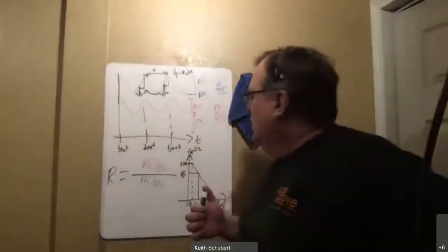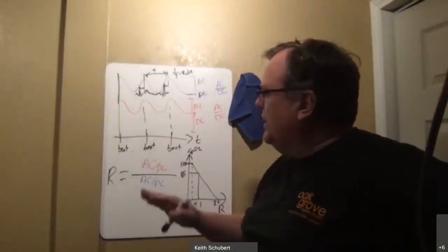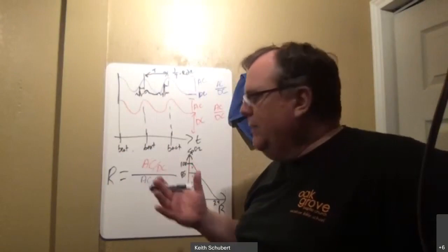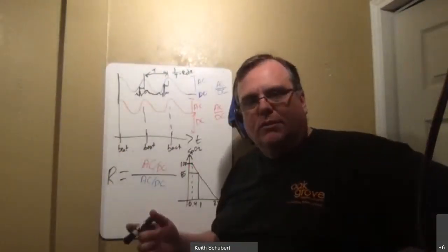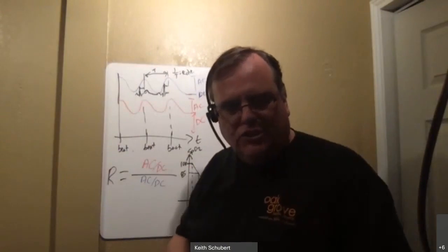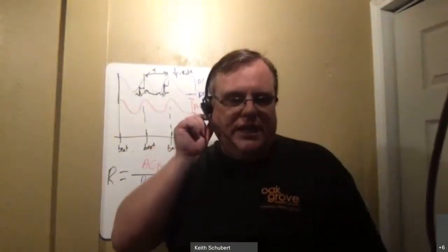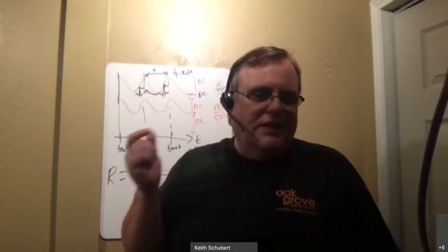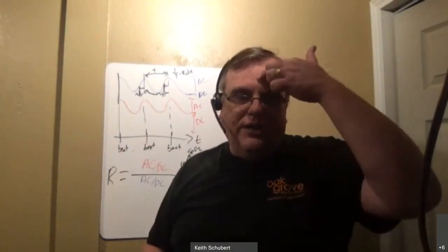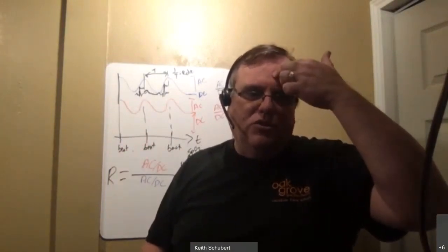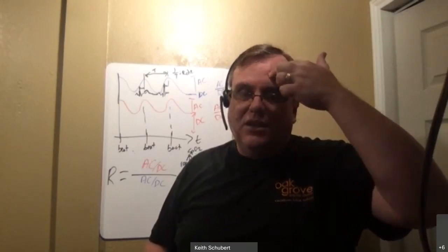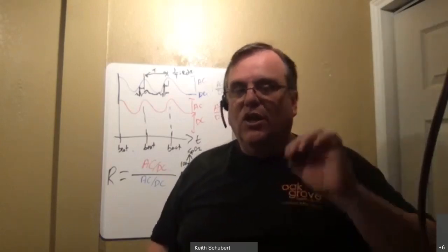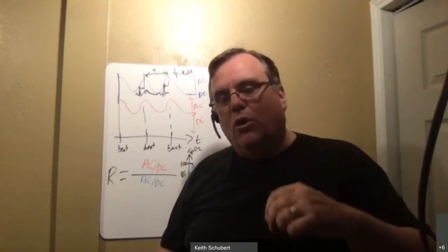Yes. Okay. So this is pulse oximetry, and it's based on all that near infrared stuff we mentioned. We've got like 2 minutes left. I just want to mention a couple other things that can be useful in this, because I don't have to just do this on a finger, right, or on an ear? You'll see some that are ear clips for pulse oximeters because your earlobe is actually a pretty good measurement spot. Your forehead's used a lot for reflection, so certain frequencies will penetrate through skin but won't penetrate through bone. And this is why green is pretty efficient, because green will go a little bit through the skin, but it won't go through bone very well.